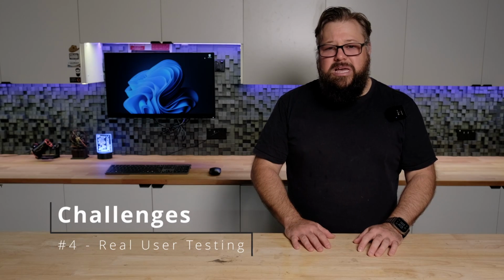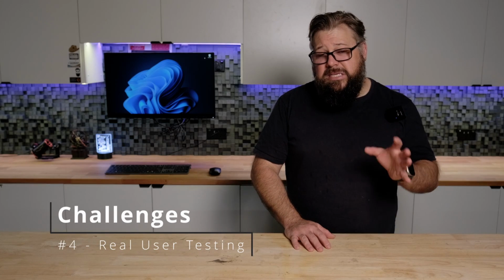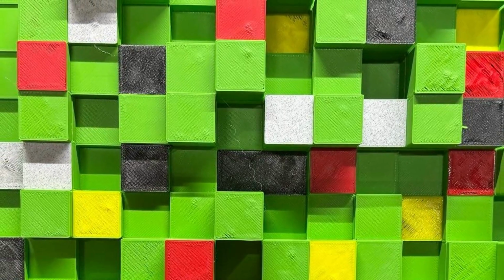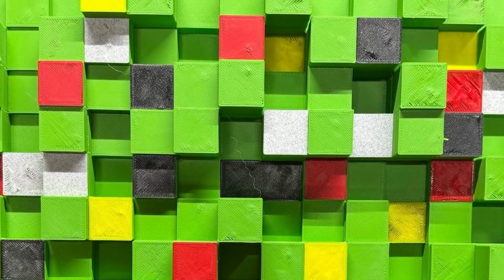And lastly, only after I printed most of my panels did I send a digital file over to Chris for a test print. And I noticed the bridging on his print wasn't great. This caused me to look closer at my own prints, and sure enough, there was some questionable bridging on my own prints. And that led me to revise my code yet again with the inclusion of a small chamfer on the inside of the model. That really improved the bridging by creating more area for the bridge to be anchored.